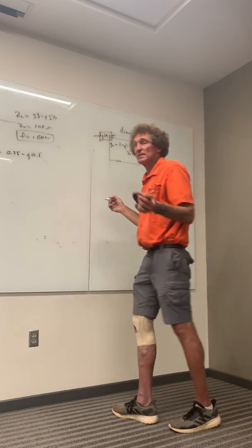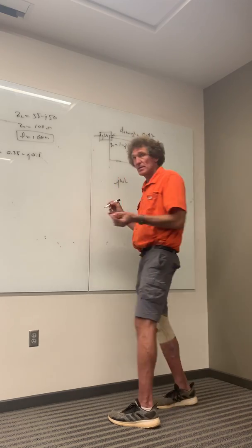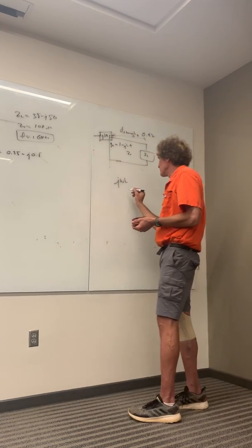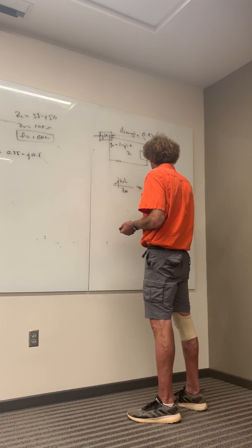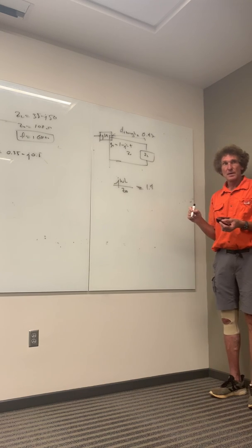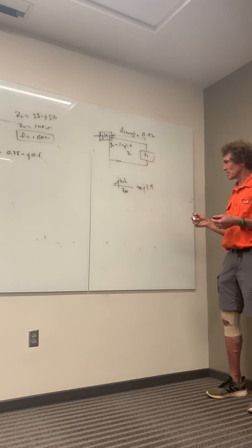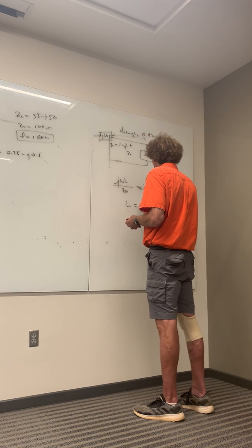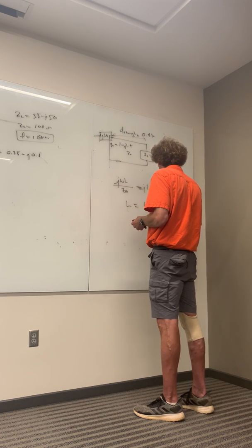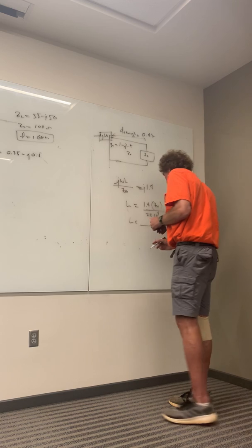Now, that's an inductor. A normal inductor has an impedance of what? J omega L, correct? But if it's normalized, you would divide that impedance by Z naught, and that would be equal to J 1.4. You all agree with me here? Yeah, J 1.4. We're gonna get rid of the J's in a second, but you're right. That means the value of L would be 1.4 times Z naught divided by omega, or 2 pi times 10 to the 9th. And what value of L is that gonna be?